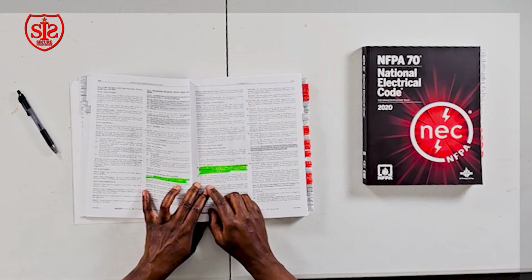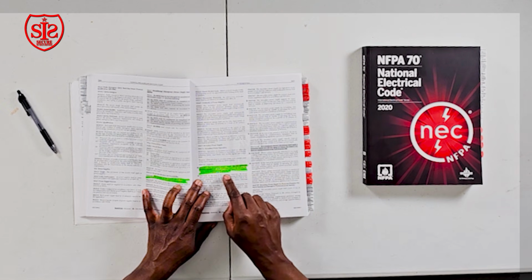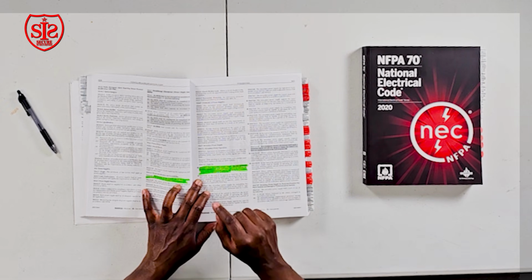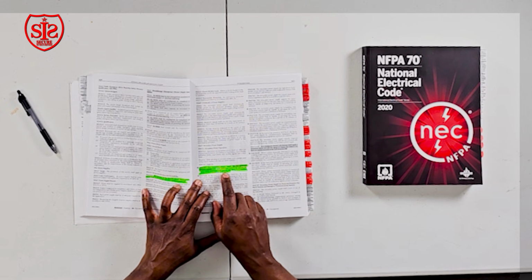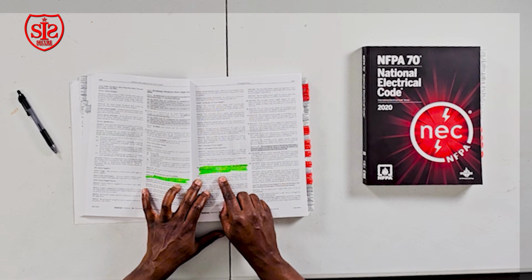Another thing you want to pay attention to is 10.6.7.2.1: The secondary power supply for the protected premises shall have sufficient capacity to operate the system under quiescent load, the system operating in a non-alarm condition, for a minimum of 24 hours. Now, if you have a voice system, your battery should be able to sound that voice alarm for 15 minutes. If it's a non-voice system, the battery should be able to operate that fire alarm system for 5 minutes.